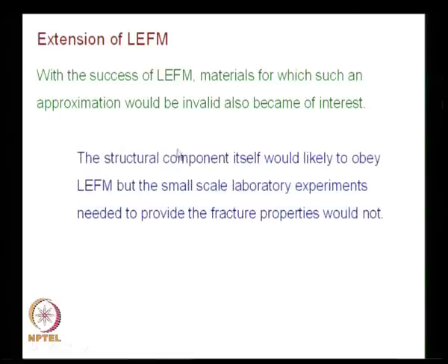And there is also another observation, this also has prompted people to go in that direction. See, the structural component itself would likely to obey LEFM, but the small scale laboratory experiments needed to provide the fracture properties would not behave in such a fashion. So, this is another angle to it.